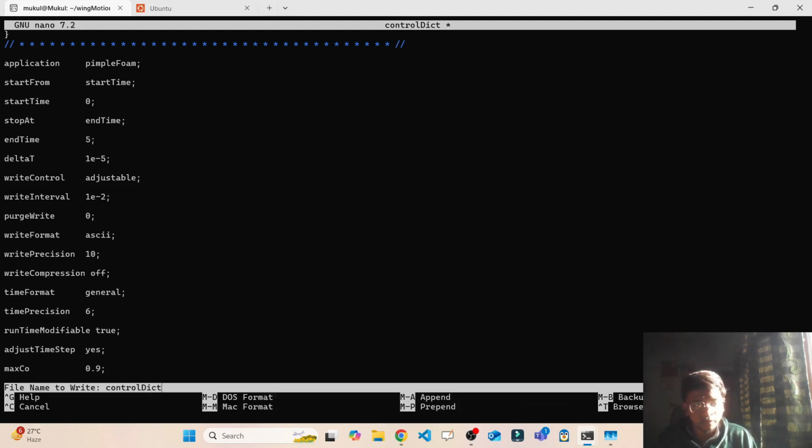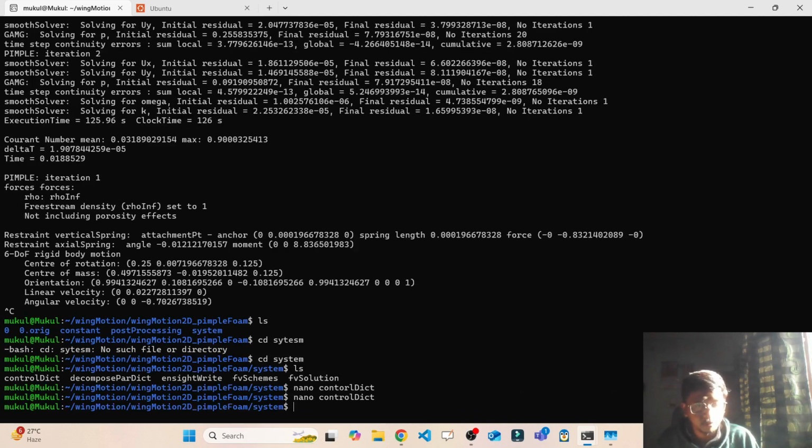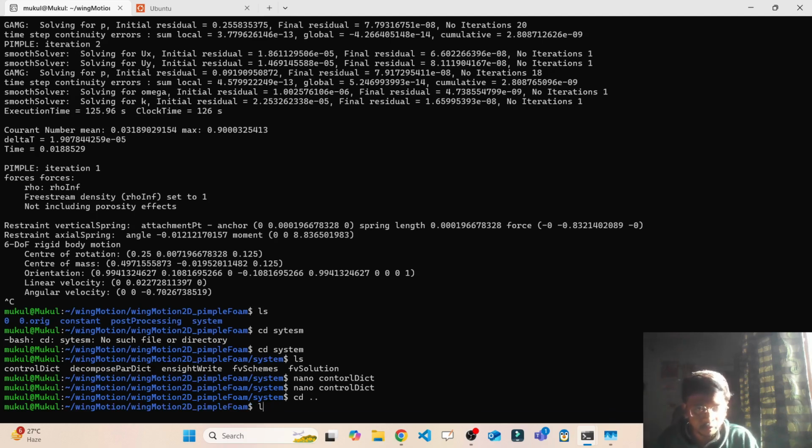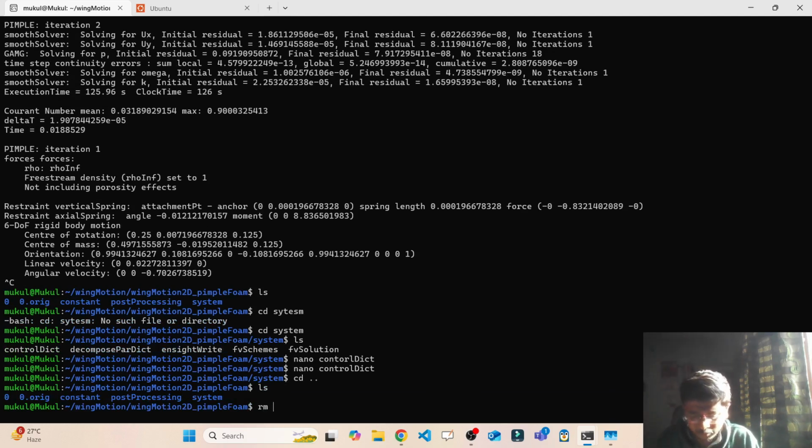Okay, no worries. With this exercise I want to show you how, in the transient or unsteady case, the simulation depends on choosing the correct delta t and maximum courant number, because for this simulation this delta t and this maximum courant number works. For others may or may not work. So I don't want to waste the time on which is working and which is not working. We will do one case of that also, no worries about that.